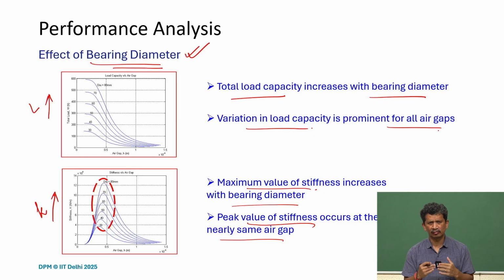So there is always a limit, and one needs to understand that, and this is also a very active area of research when we try to address these issues in air bearings. Particularly when you are working with orifice type air bearings, it's important to know what kind of instability we can have and how to avoid that.